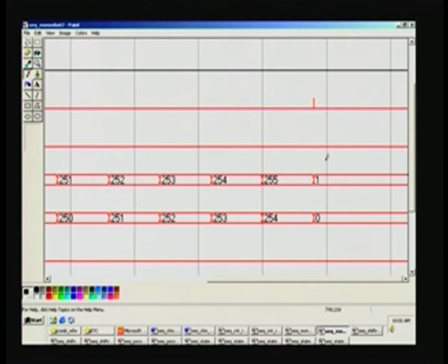But you said momentarily it's 255, right? Yes. Momentarily. Is it not supposed to be reflected there? Here. So it is so fast it is happening, right. So because the moment it goes to 255, perhaps let us examine after back annotation, let us see whether that shows up. You are right, that is a point we can examine later on, right. Right now we can't because the simulator does not contribute to the gate delays. That is why I said instead of 50 megahertz which is shown here, suppose I make it 2 gigahertz or even more, this will still show up, and unfortunately many people have jumped to conclusion based on mere simulation.